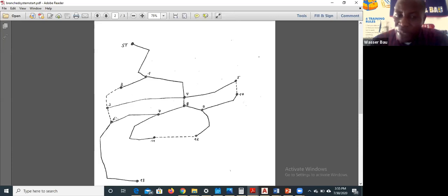And of course, this place is also what we got here, which is 0.81, what we got at node 13, plus 0.46 that we got at node 6. That was what gave us the total flow at node 6. Please take note of that. So now we have node 9 and we have node 7. So node 8 is going to be node 9 plus node 7 plus its own base demand.